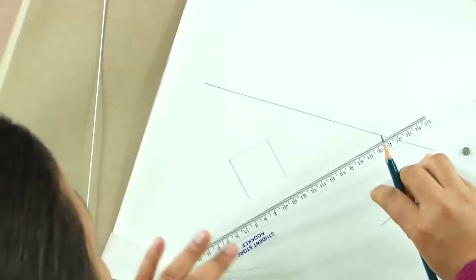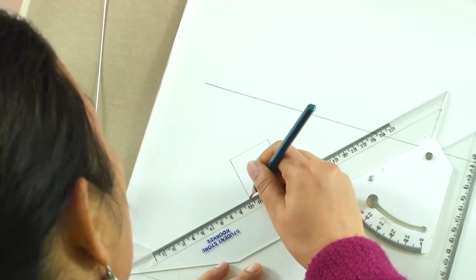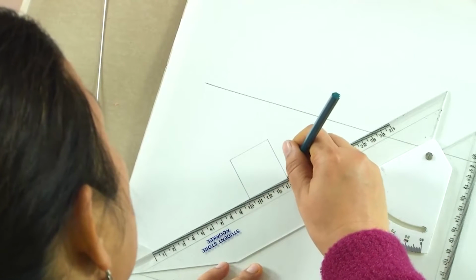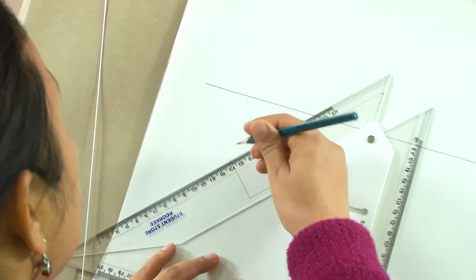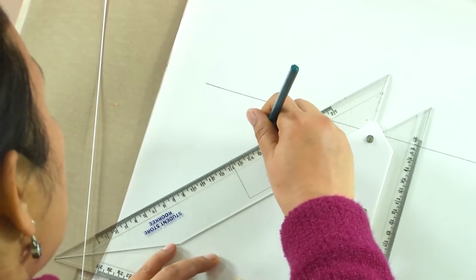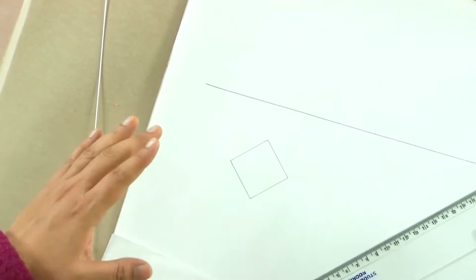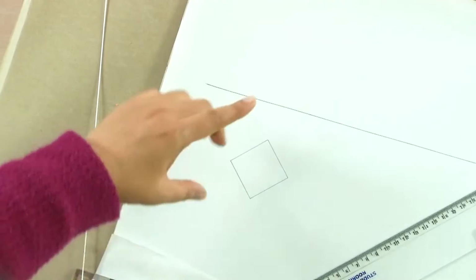This is the square which we are assuming. Now, since it has only one point in HP, that is why we have taken it as a diamond, or it is rotated. Otherwise, when we start to incline it, it will become very difficult for us to incline it about one point if we keep it straight. Now, let us take the projections of this square.